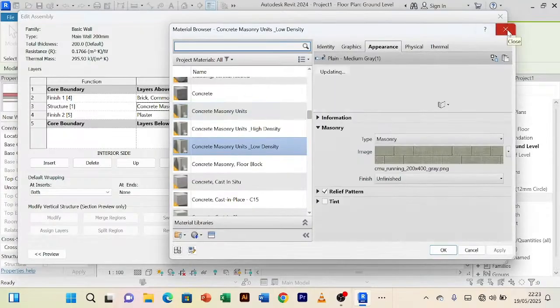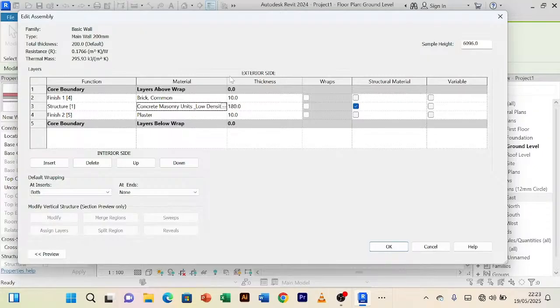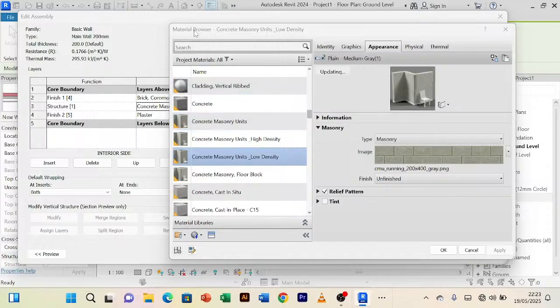it will open this menu. Just click around this line, on the material. See here, there's material. This is material. So when you click on one material, it will bring for you this box, and when you click inside the box, it will show you the browser menu. So I'll click here. So I will have the material browser, and here we really are going to create our own material.